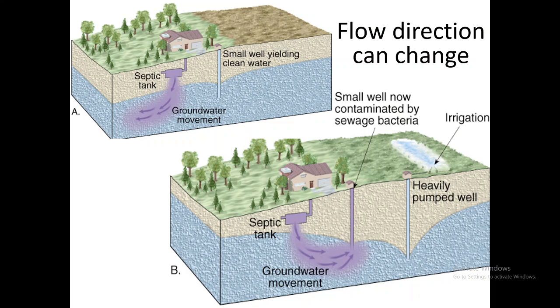Here is again the impact of monitoring wells, and how the cone of depression changes the direction of contamination. This is a previous case in which we simply studied the movement of contaminant in a typical direction following the normal slope.